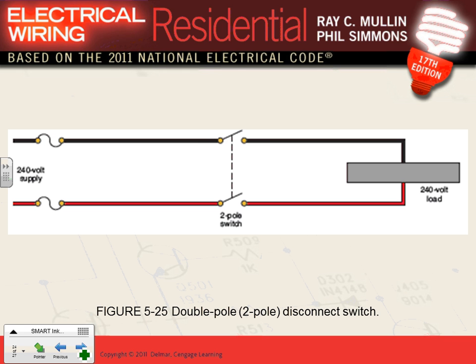Okay, so then to switch it, you have to have a 2-pole. Everybody knows what the 2-pole is. These are pole 1 and pole 2 completely isolated from each other. You land phase A here, phase B here, hot 1, hot 2, and each one goes to the other. They don't cross. This is not a 4-way switch here. And you have to open them and close them at the same time. So 1 switch, 2-pole. Have you guys seen one? It looks like any of these snap switches, except inside it has 2 terminals in, 2 terminals out.